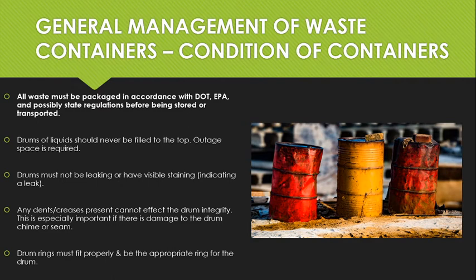Okay, so condition of containers. Most of the time this is a no-brainer, but there are times where I'll see people bring stuff back and I'm like, why would you ever transport that? So if it looks like those drums in the picture, smashed, dented, leaking, that is no bueno. All waste has to be packaged in accordance with DOT, EPA, and state regulations before being transported. Drums of liquids, don't ever fill them all the way up to the top. Give them a little bit of space, so fill them 3/4 of the way up, but leave room, and that prevents leakage, off-gassing or bulging.